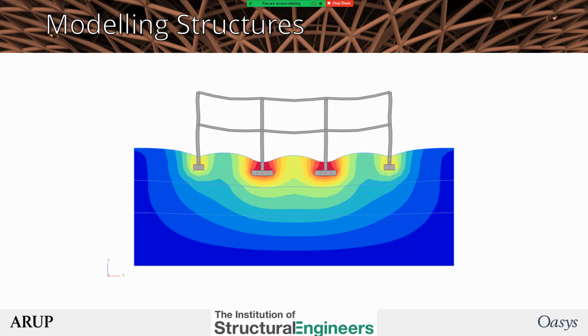Now, do we really know how stiff the beam will be? How stiff the ground? Approximately. How confident can we be with the results? Well, take a steel beam. When rolled to European tolerance standards, I'm sure South African standards are similar, its area can vary by about 4% and its bending stiffness by about 10%. This means that for every factory-made beam, there is no point calculating deflections beyond 2 significant places, or 2 single figures. Concrete beam stiffnesses will vary even more, both from the tolerances, effects of cracking, and so on.